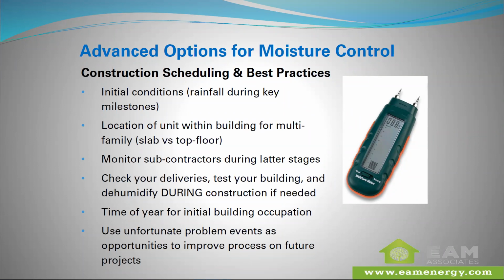The time of year is huge. When you know a building is going to have its initial occupation right in the peak of the summer, you have to be a lot more worried about that building than a building where people are going to move in January and they're going to be in heating mode for a while. If they're going to move in and crank that thermostat down because it's July, and the framing is still moist, it's going to bring out some of these issues.